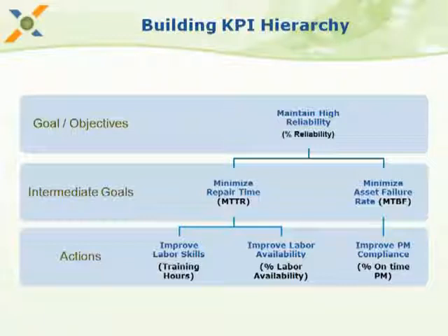From a monitoring perspective, we can monitor all our actions. In this case, how many training hours have we allocated, and our laborers are spending. Similarly, let's take minimizing failures and improving MTBF. We can improve our PM and PdM program, so you want to monitor % on-time PM.